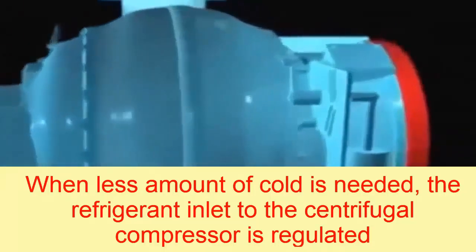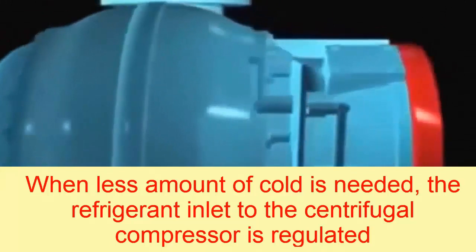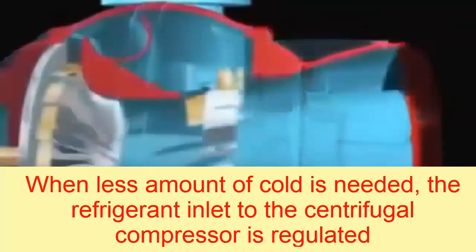So we are going to analyze how the process of regulating the thermal load of the chiller with a centrifugal compressor would be. We can see the operation of the compressor in animation. We are going to detail how the compressor can begin to regulate the refrigerant inlet. If we get a little closer to the right, we can see how we have these kinds of vanes that are going to open and close according to the amount of refrigerant that is needed.